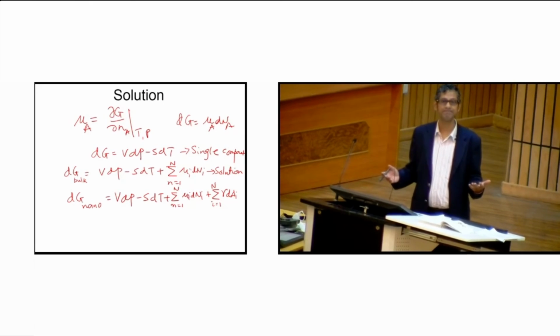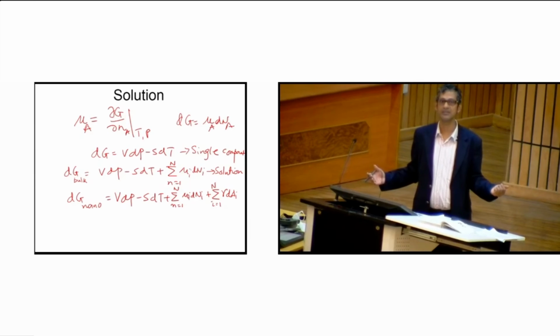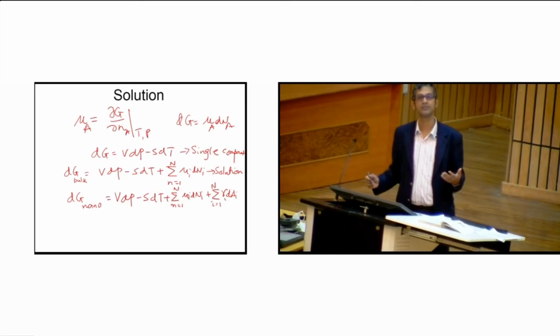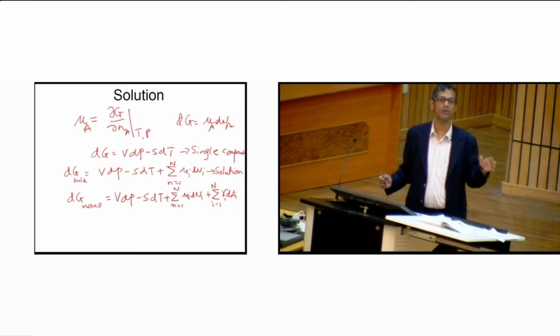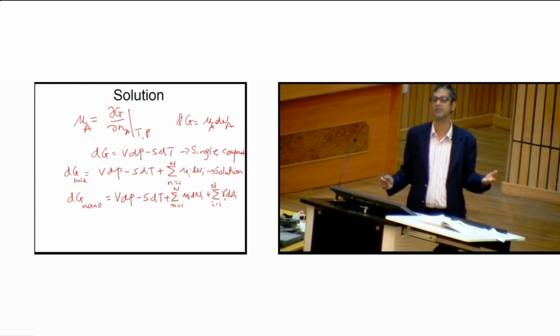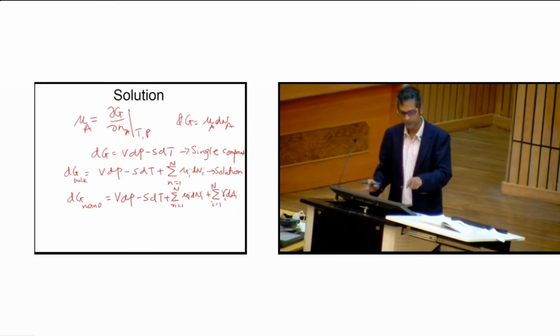Gamma into dA is the surface energy, basically gamma into A. If you have many surfaces, each surface has a different energy at different areas, so you have to multiply with that. Each surface can also have different energies. Suppose in a cubic crystalline material, the 100 facets have one energy, the 110 facets another energy, the 111 facets a different energy. So you have to add it up. So this is going to be this equation now. Remember that.